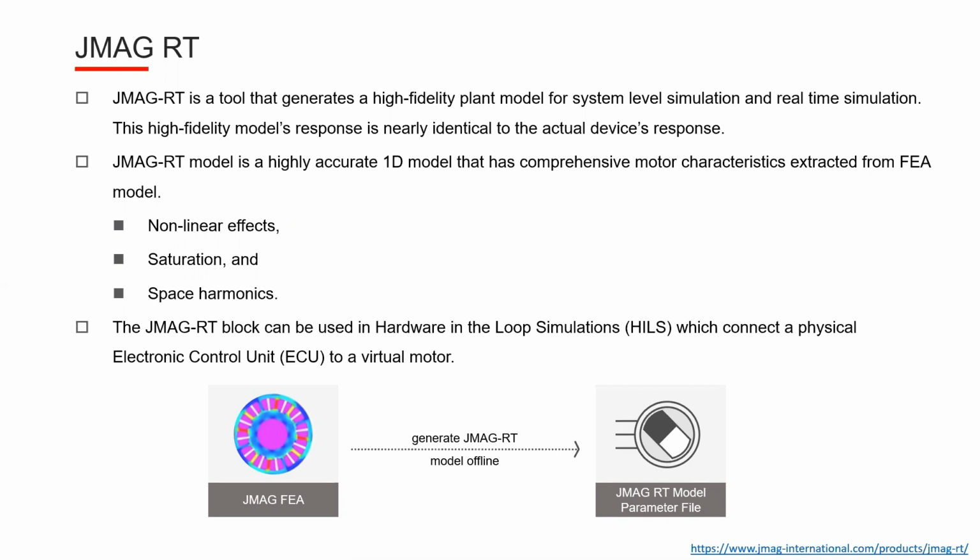Now, the JMAG-RT models are highly accurate 1D models that have comprehensive motor characteristics extracted from the finite element model. These models consider nonlinear effects, saturation, and space harmonics.